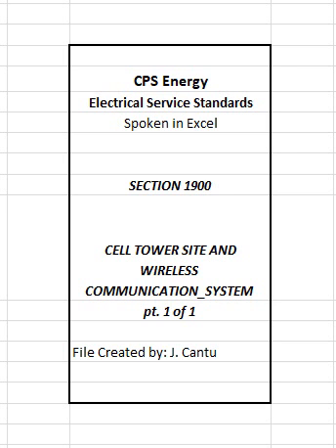1905 Technical submittal information. Customer shall submit the following information to CPS Energy for approval prior to equipment purchase and installation. 1. Meter loop drawings that indicate service disconnect ratings, conduit, and wire sizes at all points, meter socket ampere ratings, gutter dimensions, and grounding electrode connections. 2. Site plan showing location of all equipment.